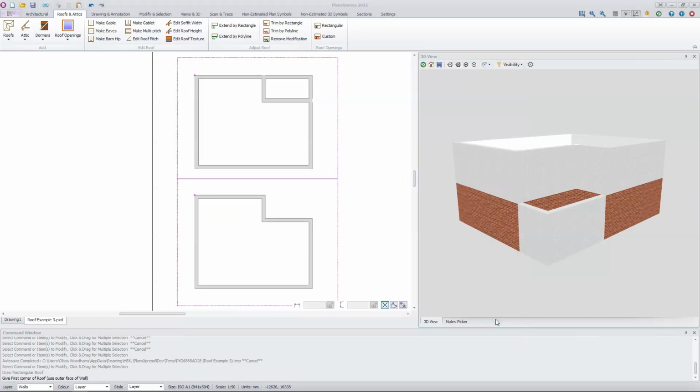As always, I'm going to follow the instructions in the command window to draw the roof. The first instruction it gives is to place the first corner of the roof. In this example, you'll see that we have snap points on 3 corners of this section of roof. The fourth corner would be trickier to place because we don't have an endpoint to snap onto. So it makes sense to use the bottom left and top right corners to place the rectangle.